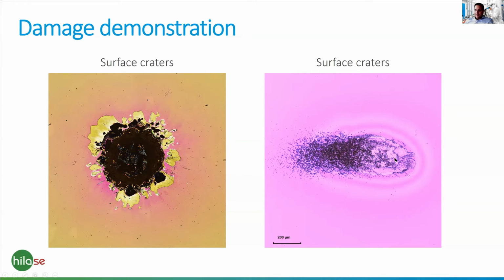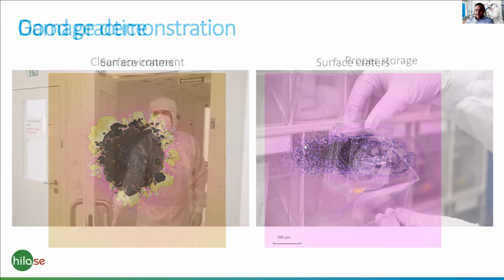The picosecond looks more dramatic because there is higher intensity, the energy comes in much shorter time, so the plasma expansion is much more rapid, and ejected particles from the crater area are smaller and fly further, which is this typical tail you can see, especially when you are damaging under some angle. So that's about the damage we can see or observe during the laser damage process.